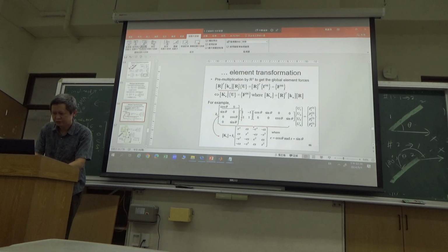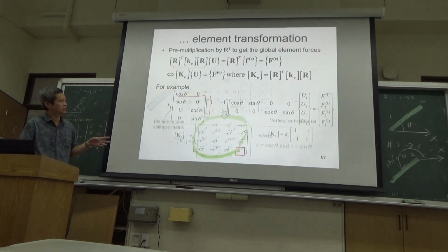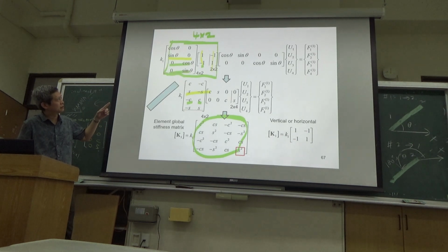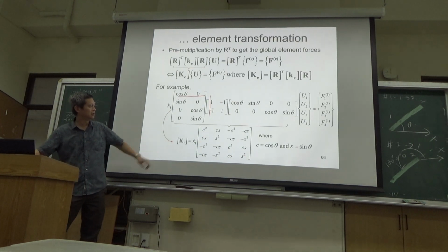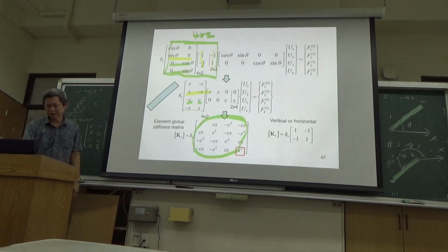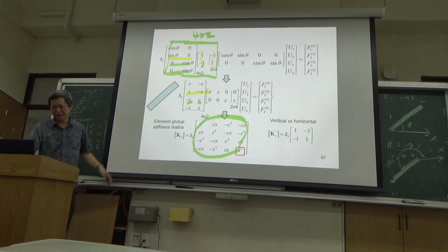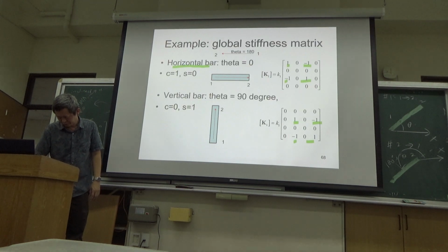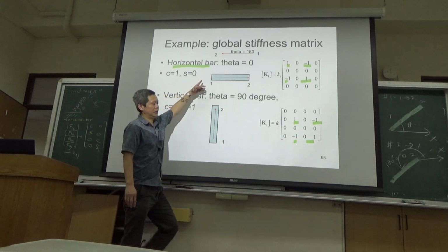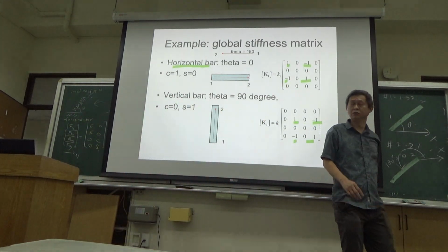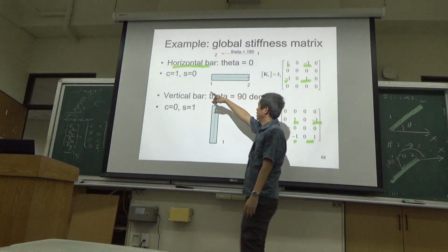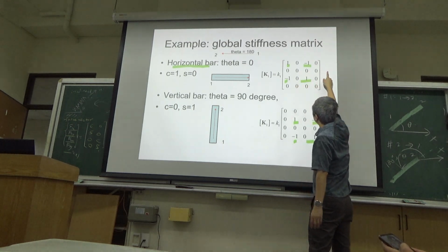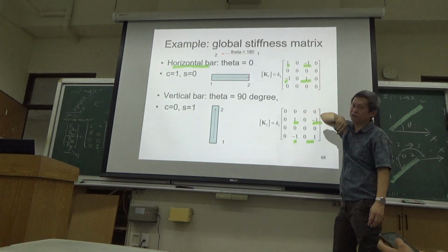So with this, we come back to the example of solution. Okay. How do you write these? How do you use this 2D element stiffness to write for a complicated equation? Okay, let's go one by one. For one horizontal element, because the angle is 0, cosine is going to be 1, sine is 0. Then you have the first row being non-zero and the third row being non-zero.